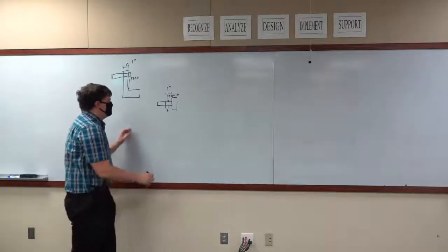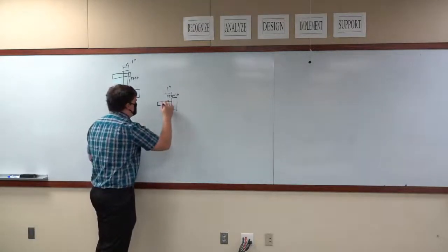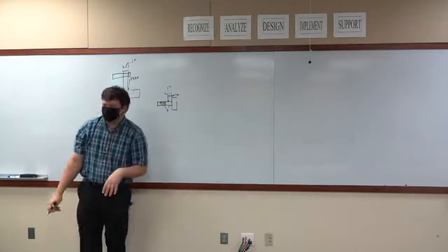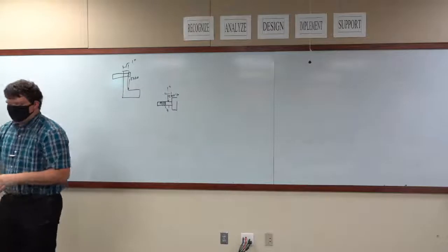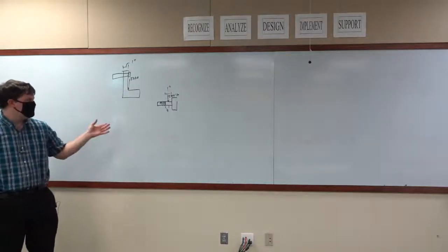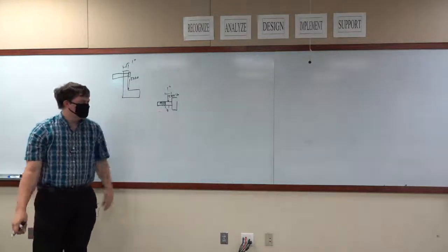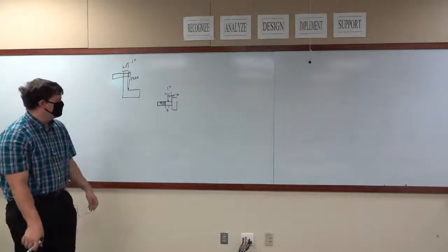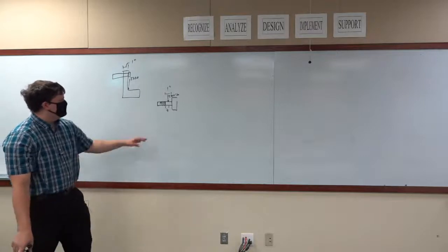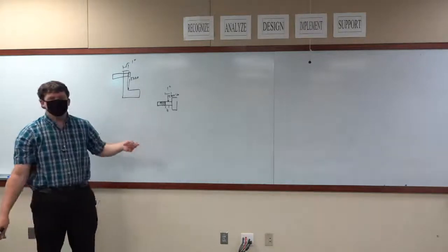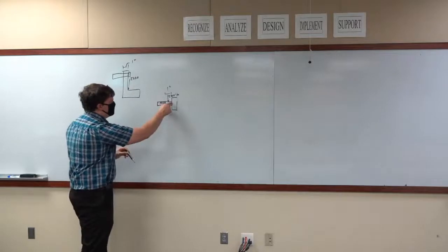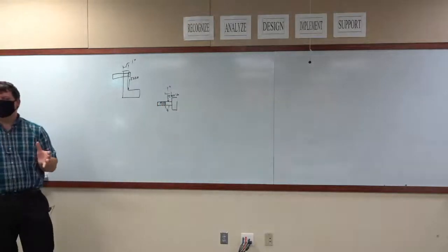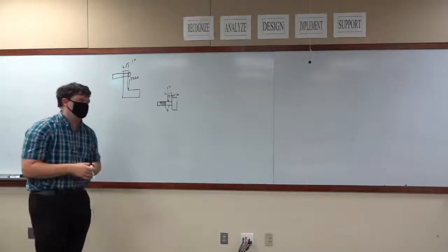Okay? Now, in actual bolt design, when it mounts into the wall, you have the first 7 threads see the most tensile force. You end up seeing about a full inch inside that it is distributing the moment load in there. Generally speaking, if you're going to mount this into a wall, you want at least as much overhang out here as you have over here. It allows you to have the same kind of moment with the same kind of forces on both sides.